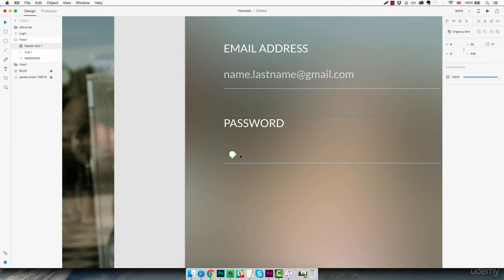We're going to select it, and then we're going to drag this little handle here towards the right side of the screen, and we're going to create about 1, 2, 3, 4, 5, 6, 7, 8 little circles here. And then when you hover with the mouse in the space between each circles, you're going to be able to decrease the space between them.